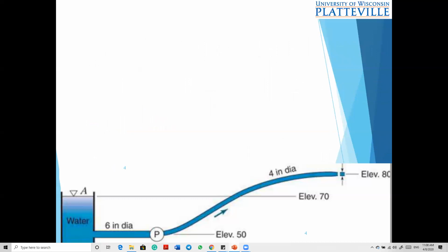All right, here is where we want to draw the hydraulic grade line and energy line. If you want, you can draw a table and see what you have. For example, you need pressure head, velocity head, and elevation head, right?